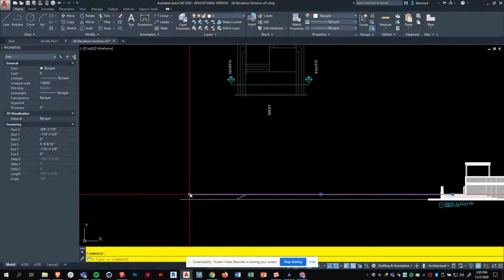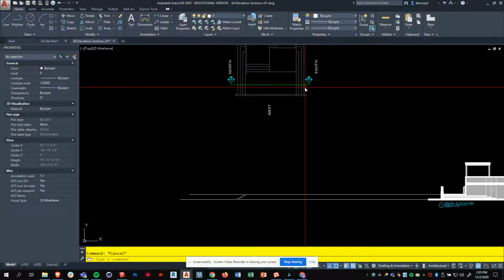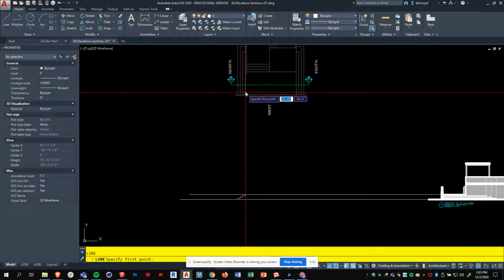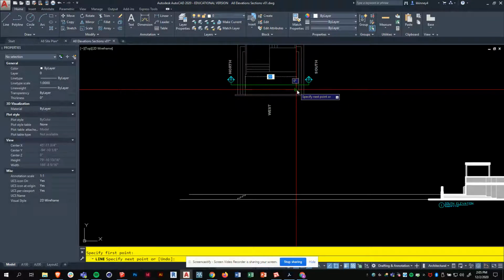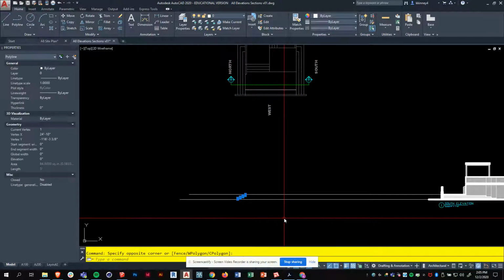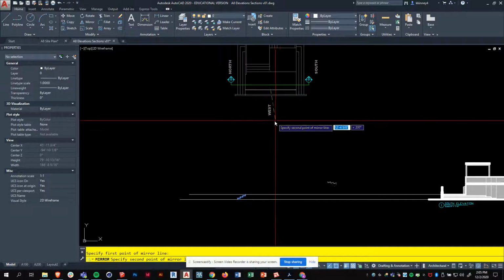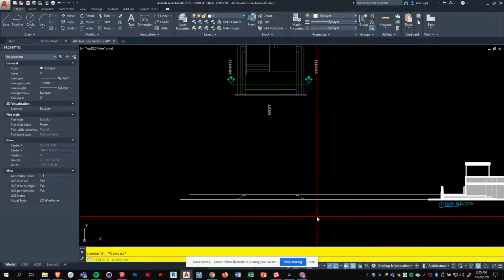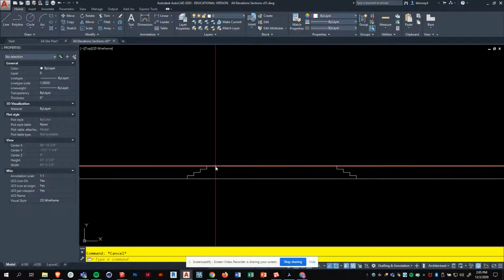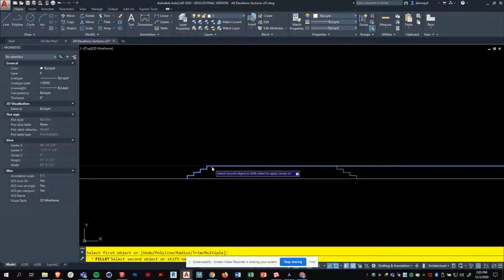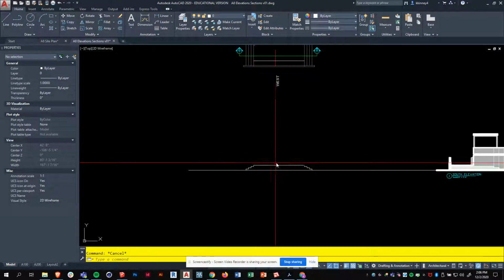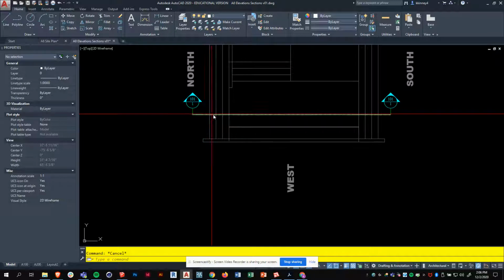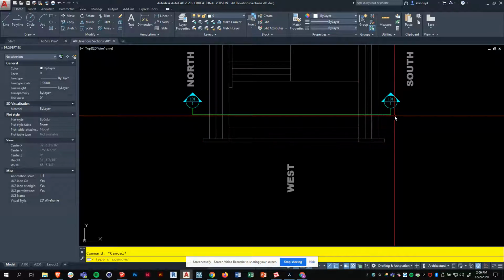Okay, now I can do the same thing over here. Now here's a trick. These stairs and these stairs match, right? So I could say, I'm going to just draw a line right here, and I'm going to grab these stairs and I'm going to mirror them about that line and click. So now I'm going to match these stairs to that initial line I drew. And look at that. I have my cut line, actually my entire cut line going through the structure right there.